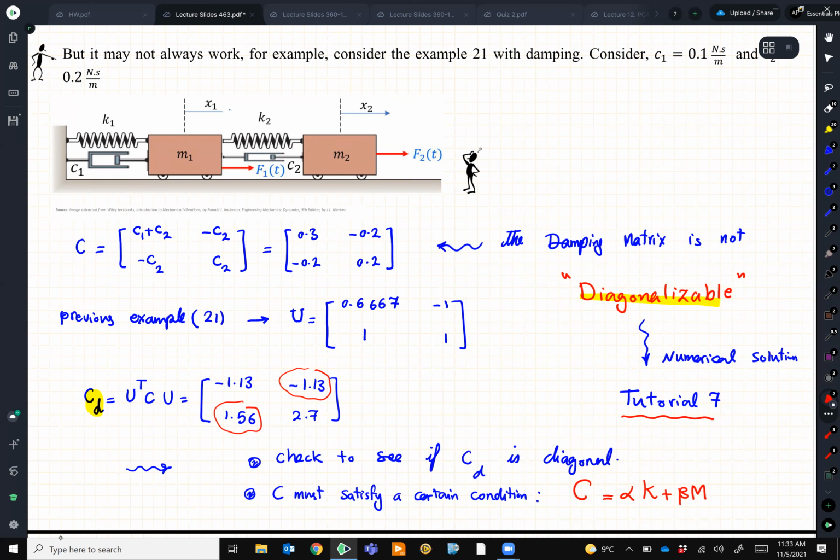But in a very simple word, as a quick check, whenever your damping matrix can be written as coefficients of your mass and your stiffness matrix, we'll see mathematically the CD will be diagonal. And there is a terminology people use, if you just want to write it down, just to know.